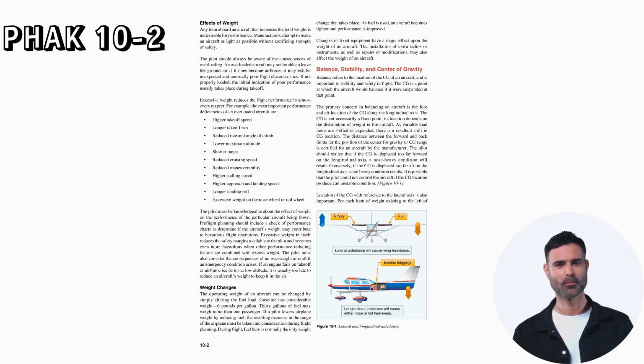The pilot must be knowledgeable about the effect of weight on the performance of the particular aircraft being flown. Pre-flight planning should include a check of performance charts to determine if the aircraft's weight may contribute to hazardous flight operations. Excessive weight in itself reduces the safety margins available to the pilot and becomes even more hazardous when other performance-reducing factors are combined with excess weight. The pilot must also consider the consequences of an overweight aircraft if an emergency condition arises. If an engine fails on takeoff or airframe ice forms at low altitude, it is usually too late to reduce an aircraft's weight to keep it in the air.